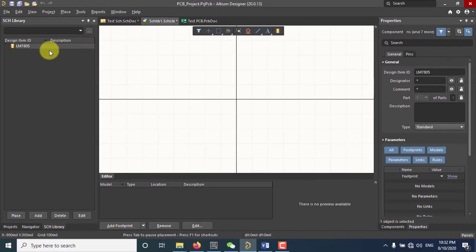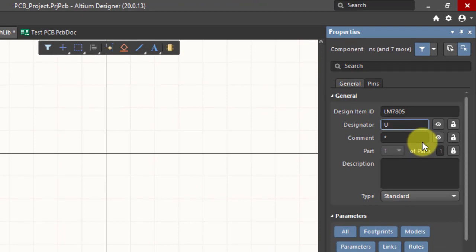Alright, so now back to the schematic symbol. Here let me use the designator U, and I'll also put a question mark to remind you that you need to assign a number, you need to replace this question mark. And I'll just put a comment that it's a regulator IC. Okay, that's just for beginners. If someone doesn't know what this guy is, or if you forget in future what this is for, it will give you an idea. Right, so that's the settings we need.